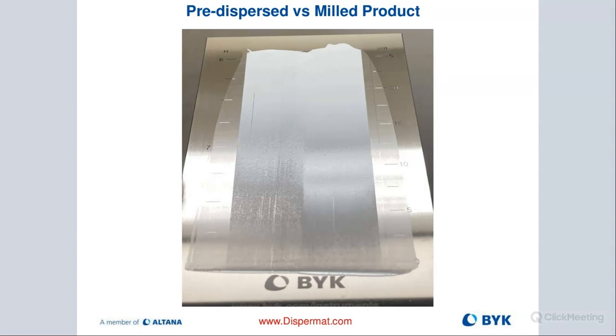So here's a great example. On this grind gauge drawdown, on the left side we see a product that was pre-dispersed with a dissolver for about 30 minutes. It probably started out at about 100 microns of particle size, and we were gradually reducing these larger agglomerates down to the aggregate level. But as you can see, it doesn't really look all that good. Then when we continued milling, we achieved a much more consistent, better looking product. That was the result of further reducing our particles from the aggregate level down to the primary particle size.